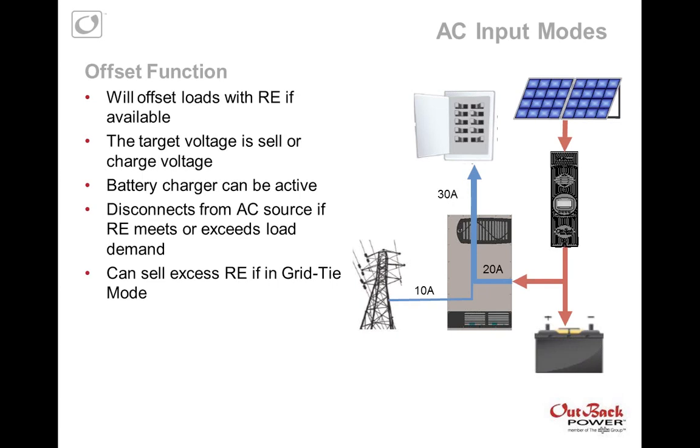I know in Ontario, I think, they don't allow battery-based systems, and I think part of that issue is that they don't fully understand how our rating might work. We're working with some utilities here because a lot of utilities don't understand battery-based inverters, but with this offset function, it allows you to stay connected to the grid without putting energy out onto the grid, but you're not stranding that renewable energy because you're allowing your loads to consume it.